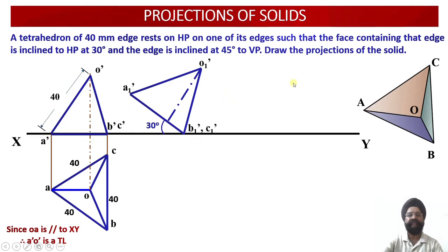So using rectilinear distances, we have been able to transfer this front view elevation view in the third view. So the third view is always a rotation or translation of the previous view, that is the front view elevation. Now having obtained this view, how many points are there? 1, 2, 3, 4. So these are 4 points which I need to project downwards. And the projections from the plan projection points will be drawn horizontally.